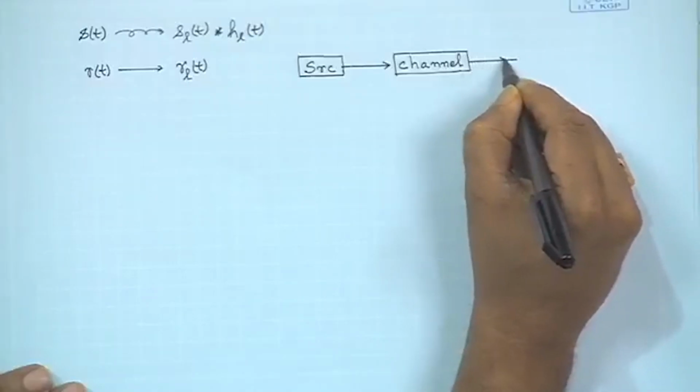And in the previous lecture we have seen that the output, the low pass equivalent RL of f, is equal to the Fourier transform of the signal multiplied by the Fourier transform of the channel impulse response. So that means a multiplication in the frequency domain, and it's a convolution in the time domain. It changes the signal as if there is a filtering process.